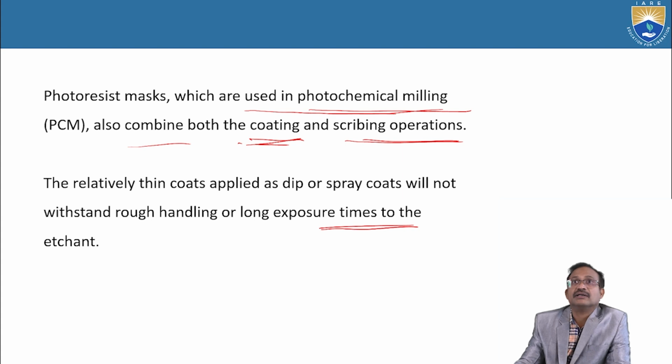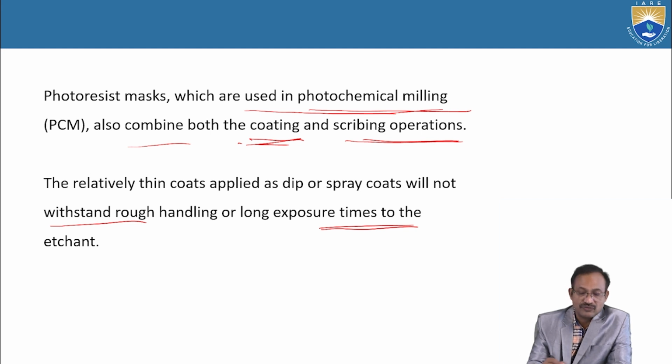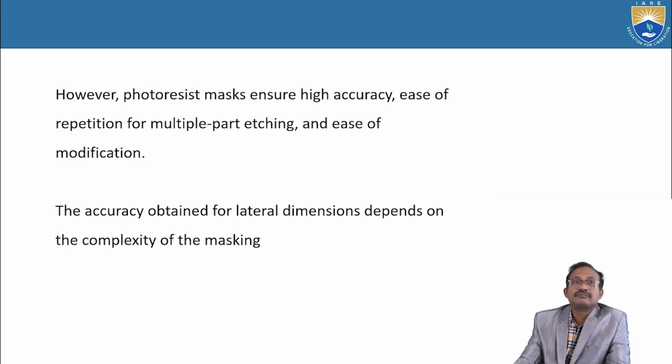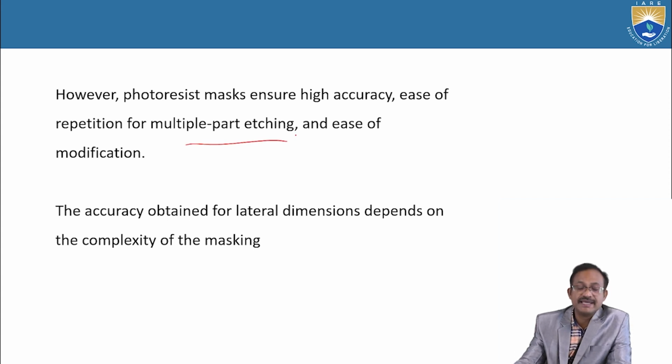When it is rough or when we go for long exposure times, thin coated sections will not withstand. However, photoresist mask ensures high accuracy, ease of repetition for multiple part etching and ease of modification.